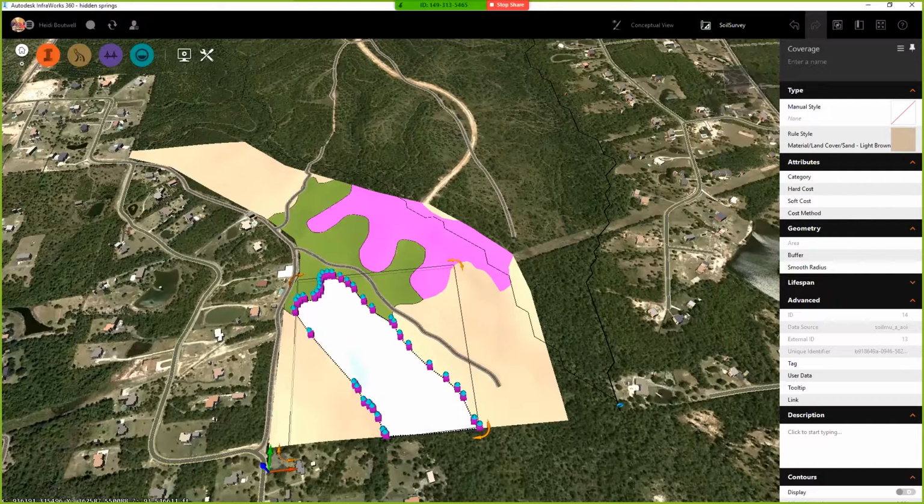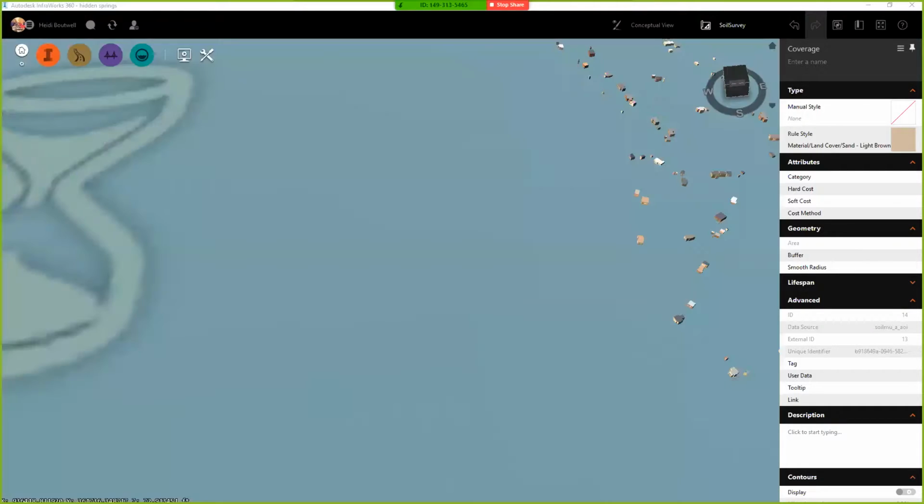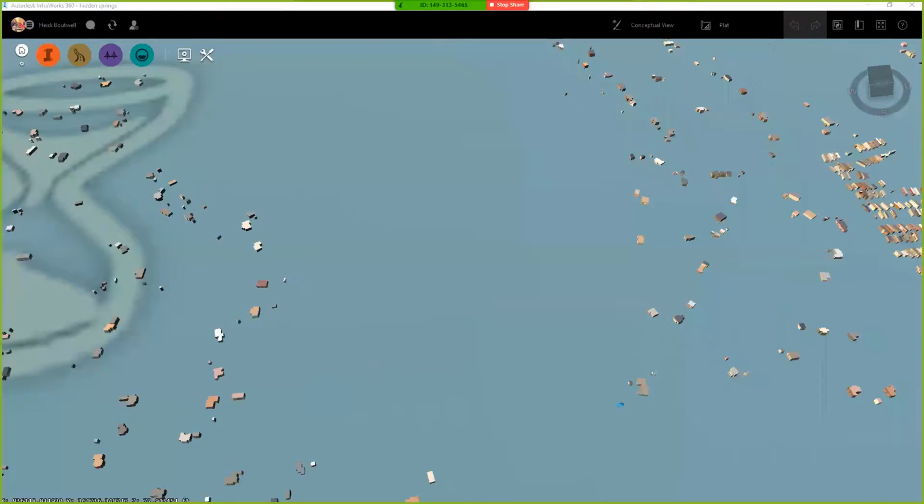What about my plat? So I've got a plat that I was given by the surveyor that they went through and took the time and actually made. I brought it into Civil 3D, and I made it into parcels. Took me a little while to do that, but I'd really like to see what it looks like here so I can show my client. And this will take a minute or so to come over and regen once it gets there. And SDF files, depending on what you bring in, can take a while, and some may not. The plat takes a little while to get in.